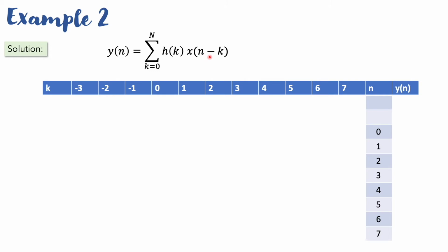So first we get x[minus k], which is the flipped version of x. Since x had samples from 0 until 3, that is 0, 1, 2 and 3, making 4 samples, when we flip it, it will go to 0, minus 1, minus 2 and minus 3. We have extended from 0 to minus 1, minus 2 and minus 3, depending on the number of samples in the original input sequence.